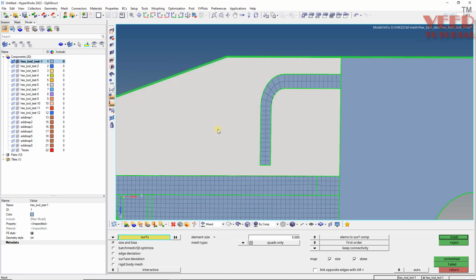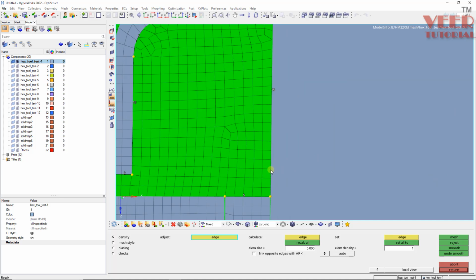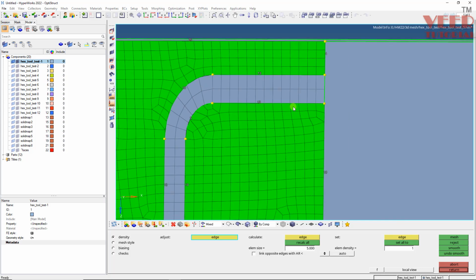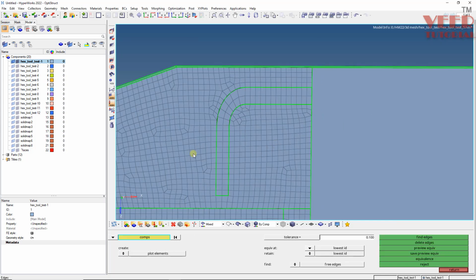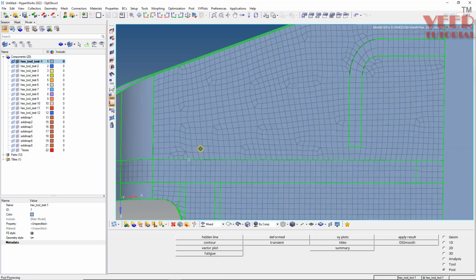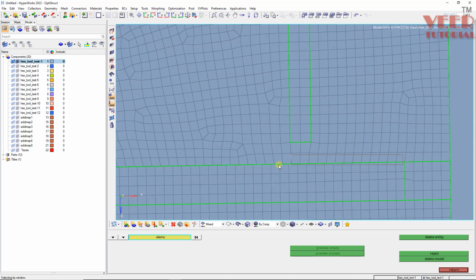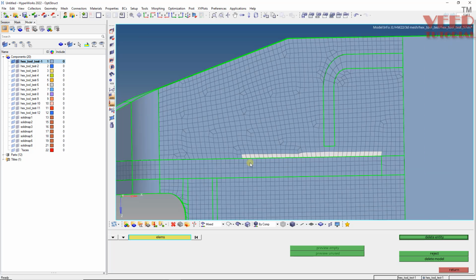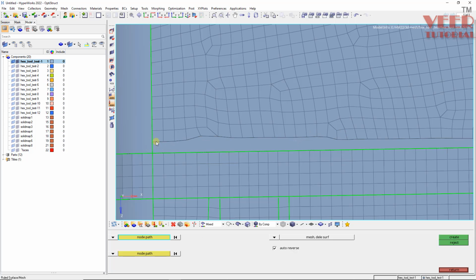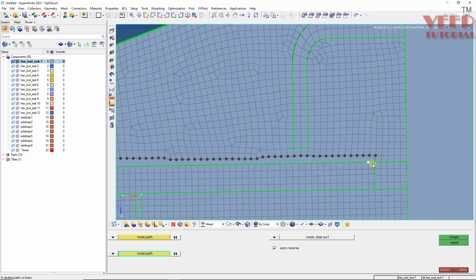F12 and select this complete face, and there is no connectivity here, and there is some connectivity here, but here is missing. Okay, we will first do the equivalence, and wherever there is no connectivity we will rule it. So F2, here there is no connectivity, so pick this layer up to here, delete this, then ruled from here to here, once again ruled from here to here,